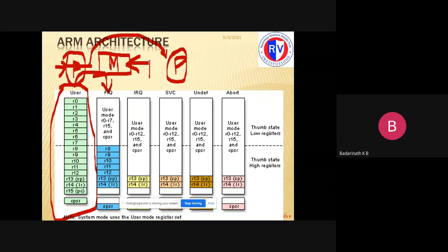That's what we have discussed, the modes. The moment the request comes here, the microcontroller, as designed by the chip manufacturers, switches automatically into the FIQ mode. Whenever you go to the FIQ mode, you always have to remember that you are in the middle of some other program execution. All these general purpose registers are already used by the programmer to implement certain logic in this program based on his requirement. Some registers may be holding data, some may be keeping an address, but everything is engaged.